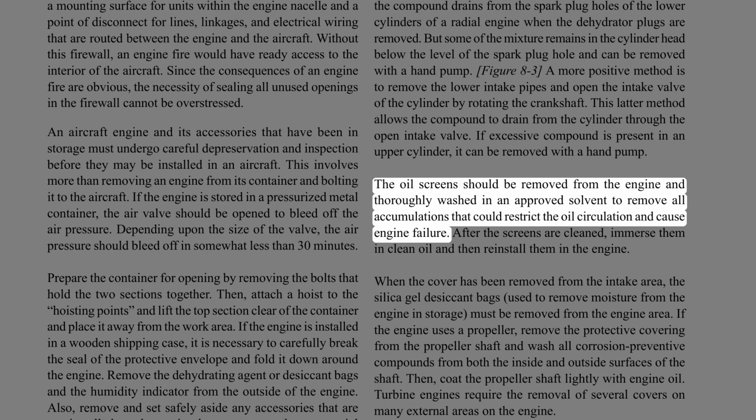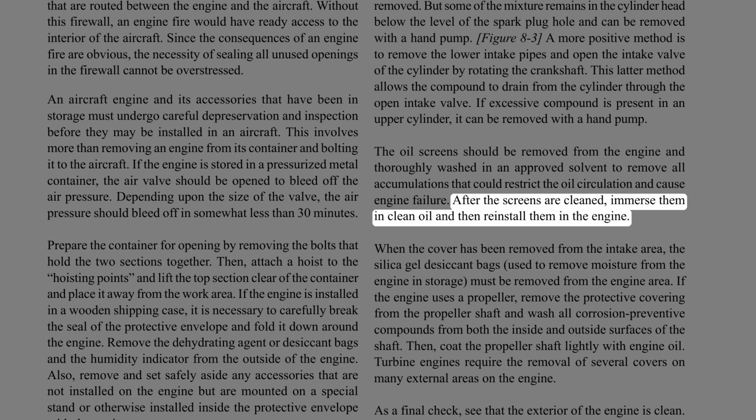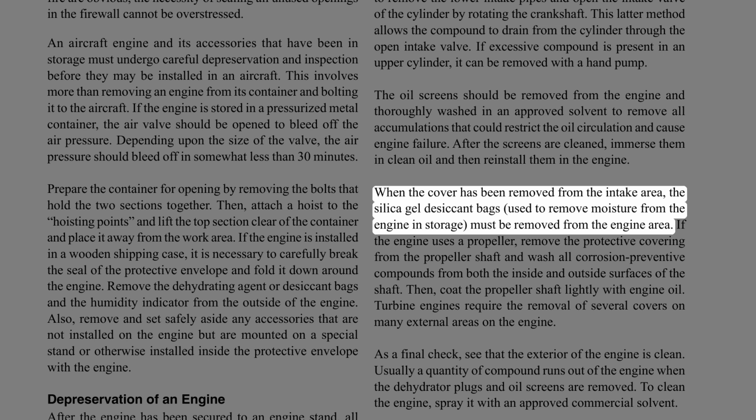The oil screens should be removed from the engine and thoroughly washed in an approved solvent to remove all accumulations that could restrict the oil circulation and cause engine failure. After the screens are cleaned, immerse them in clean oil and then reinstall them in the engine. When the cover has been removed from the intake area, the silica gel desiccant bags, used to remove moisture from the engine in storage, must be removed from the engine area.